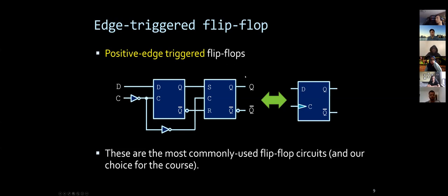So essentially, we build a circuit called a flip-flop, and this is the symbol used for it. And this one is going to be triggered when the signal goes from low to high, and that thing would flip only once over the cycle of the timer. So if you look at the waveform that I showed in the lecture, you're going to see that the flip-flop changes its value when the pulse goes from low to high, and then it goes from high to low and from low to high again, and it flips again, right? So it doesn't flip in between. It only flips once, and that's what you really want, right? That's essentially a very stable memory, something we can use moving forward.